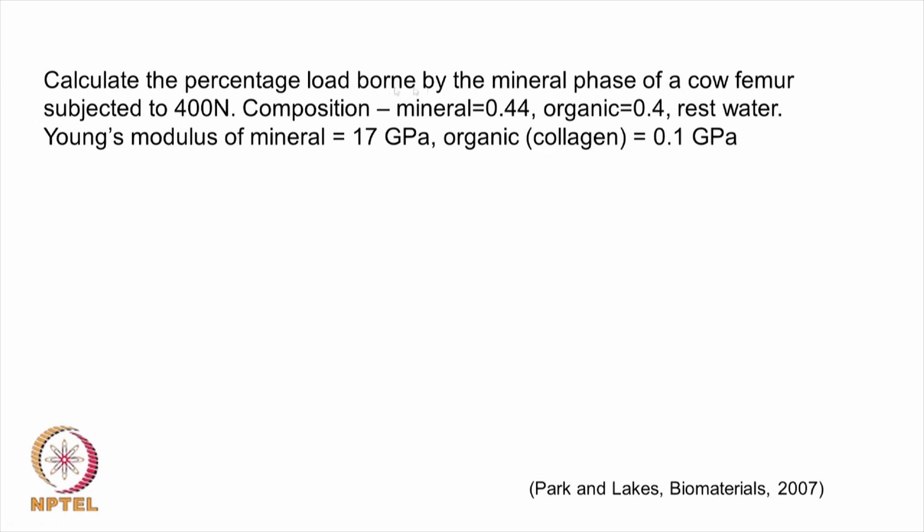Calculate the percentage load borne by the mineral phase of a cow femur subjected to 400 Newton. As you know, it has got mineral, it has got organic and then water. So, mineral is about 44%, organic is 40%, and there is water. So, water will not take any load. So, mineral and organic. Young's modulus of mineral phase is 17 gigapascal. Young's modulus of organic, which is collagen, is 0.1 gigapascal. So, the load borne will be proportional to the ratio of the composition. That is simple actually.